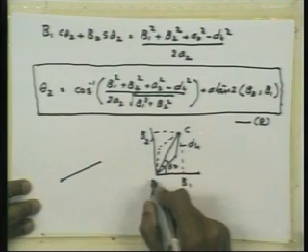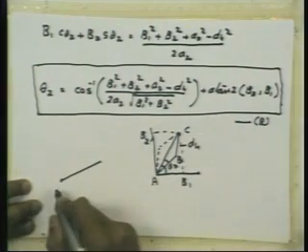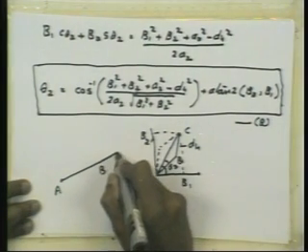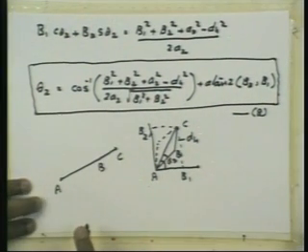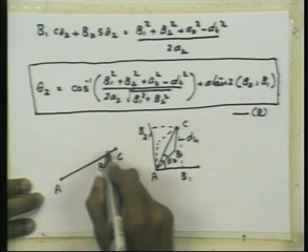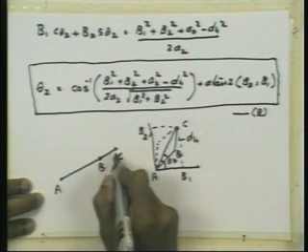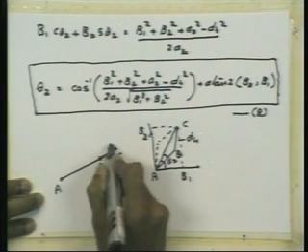So if you consider that, let us call these points A and B. So if this is A and this is B, and if D4 is this length, the set of points C can reach are obtained like this. Rotate this link BC with B as center, you get this circle.